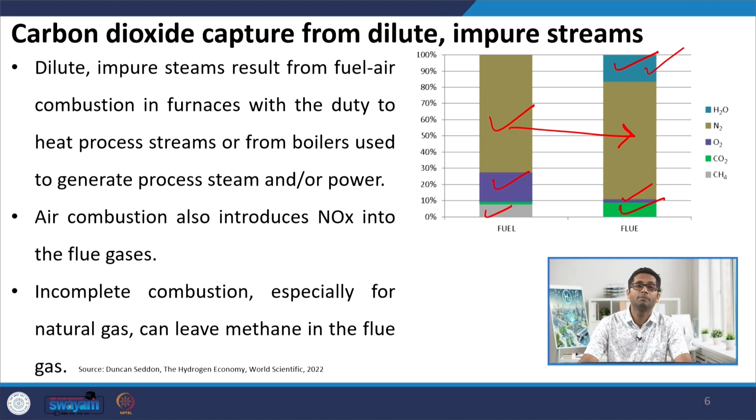And as we have discussed in the previous classes as well, one way to avoid these gases altogether is to go towards a methodology that is based upon partial oxidation. In partial oxidation, in the methane reformer, you are reacting the methane with oxygen, and it's an exothermic reaction occurring at around 1500 degrees Celsius. So that entails I do not need to burn a fuel outside the reactor, which results in this flue gas. So I can altogether avoid the production of this flue gas by adopting a process like partial oxidation. Companies like Shell have been adopting the partial oxidation process because they would want to aim for blue hydrogen rather than green hydrogen, where they are capturing the CO2 that is coming from the hydrogen production.